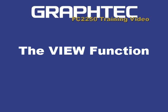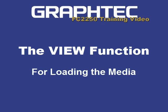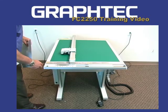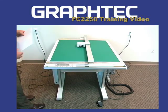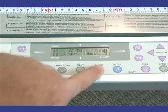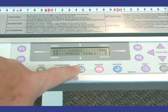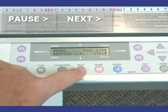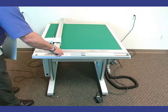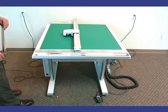The view function is a neat tool in that when you need to load the material or you need to view your drawing, it's an easy way of getting the bar and the tool head completely out of the way, moving it up into the upper right hand corner. In order to use the view function, the first thing you do is press pause, then next, and then F4 for view. The plotter will move its head and the arm completely out of the way so that you can load media.